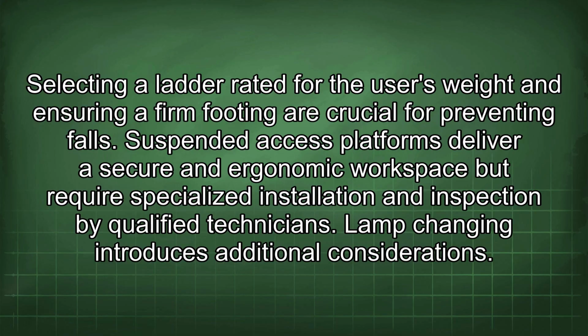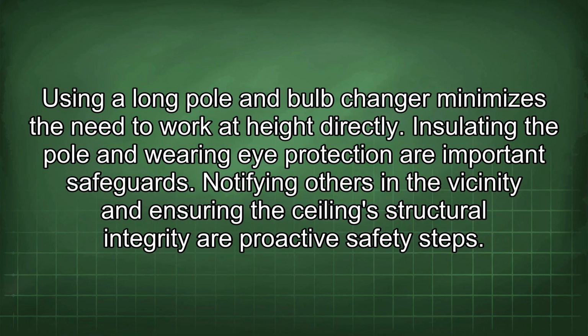Lamp changing introduces additional considerations. Using a long pole and bulb changer minimizes the need to work at height directly. Insulating the pole and wearing eye protection are important safeguards. Notifying others in the vicinity and ensuring the ceiling's structural integrity are proactive safety steps.